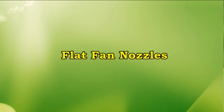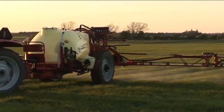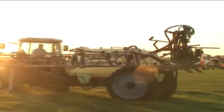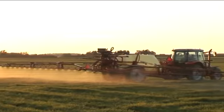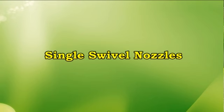consideration. Flat fan nozzles. These are used largely for broadcast spraying, where foliar penetration and coverage are not essential. The best operating pressure for flat fan nozzles is 15 to 30 psi, which produces coarser droplets that are not susceptible to drift.